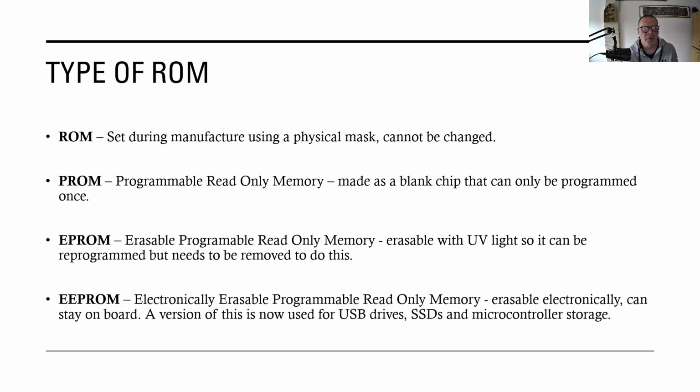Then programmable read-only memory, PROM. This is ROM that's made as a blank chip, and you can program it once. So you could buy bulk blank chips and then program them as you want them and install them on your device. But those are written off the board, and then put onto a board and installed.